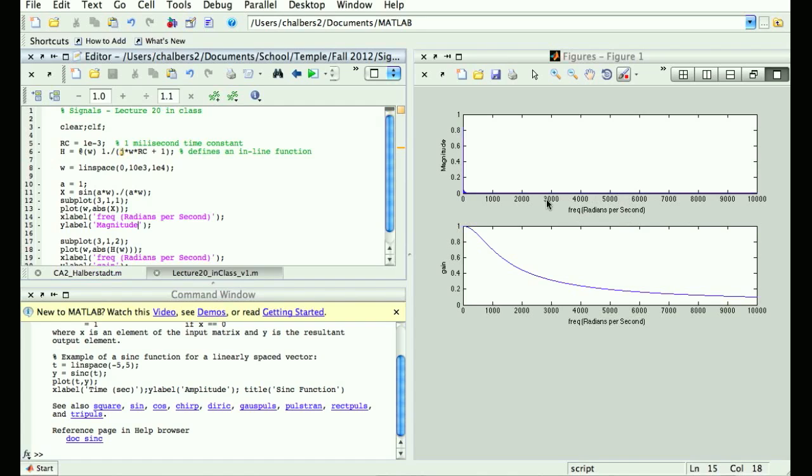I've got like 1,000 and 2,000. So yeah, all the action on the sinc pulse is happening at like 3 and 6 and 9 radians per second. And over here I'm talking about thousands of radians per second. So why don't I make my rectangular pulse skinnier? Okay, that should solve the problem.